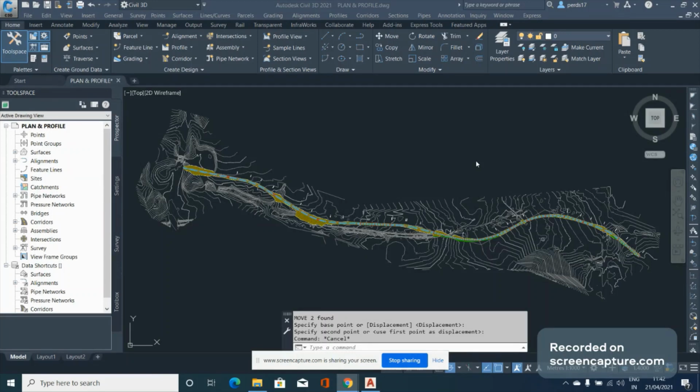Civil 3D has a tool called Plan Production where you can automatically create sheets, and also manage those sheets in the Civil 3D environment. Where you have a long highway, like 10 to 15 kilometers, you have to generate a lot of plan and profile sheets or plan and plan sheets or section sheets, and creating those sets is a very tedious task because you have to align all the viewports, put in all the information, and fill it in. Even more tedious is managing those sheets.